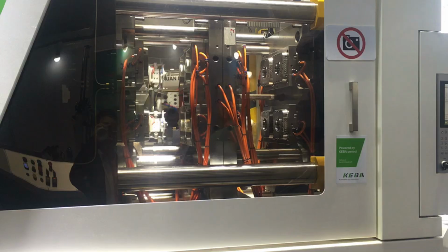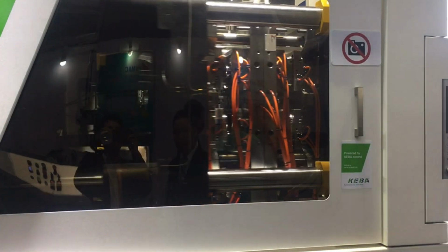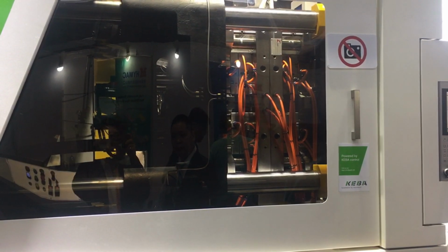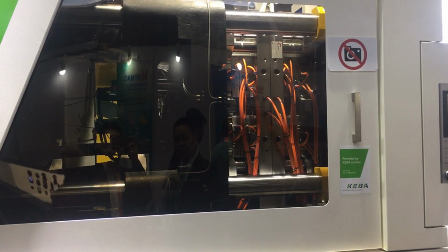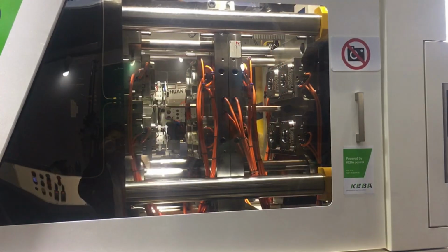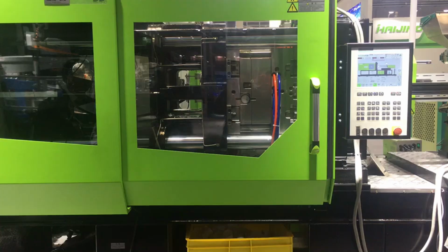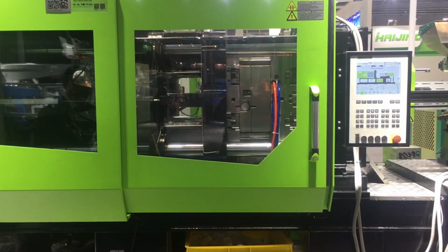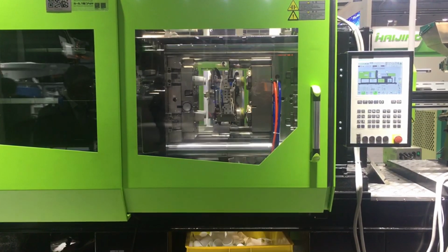Plastic injection filling is followed by the pressure holding stage. The purpose of pressure holding is to fill the cavity with plastic melt. Due to the cooling contraction of the plastic, it is necessary to maintain a certain pressure for a certain period of time to continue to replenish the plastic melt into the cavity to prevent defects such as shrink marks and voids in plastic products. The holding pressure is generally lower than the injection pressure, and the holding time is determined according to the thickness and size of the plastic product and the type of plastic.